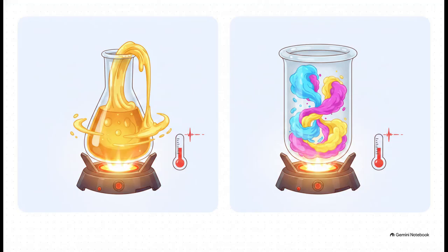Now, temperature plays a massive role here, but it acts completely differently depending on the state of the matter. In a liquid, viscosity decreases rapidly as temperature goes up. Think about heating up that honey in the microwave. It pours way faster, right? But in a gas, viscosity actually increases when the temperature goes up. Pretty wild, right? But it's true. So when heated, liquids flow more easily, whereas gases actually flow more slowly. This is an absolutely vital principle to remember for process control, because temperature shifts in your pipes are going to fundamentally change how your product flows.